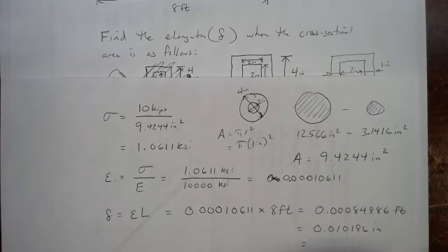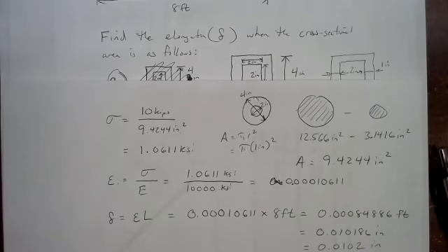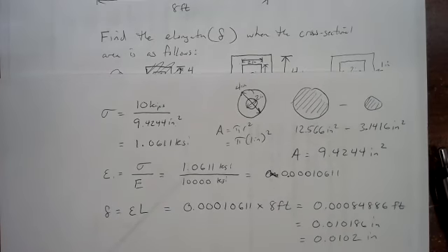The round off error is relatively benign here, but yeah, if we wanted to round it off to 3 sig figs, we'd have 0.0102 inches, so 10.2 thousandths of an inch. Yep, that'd be pretty typical. So that's not too bad.